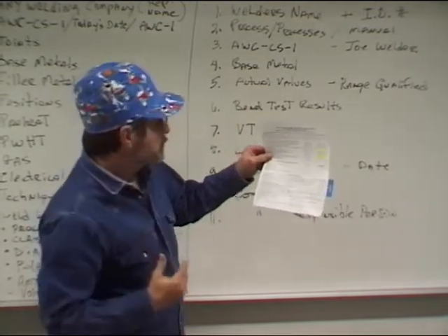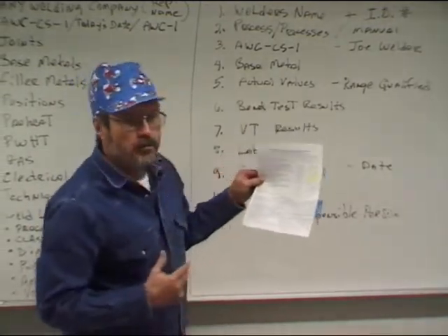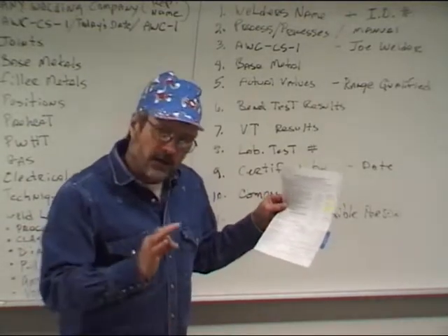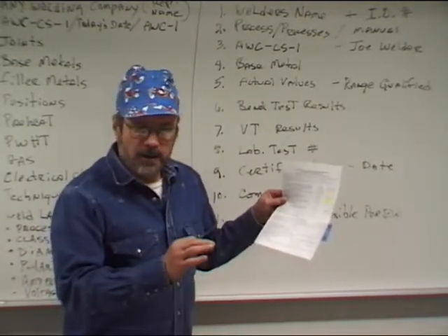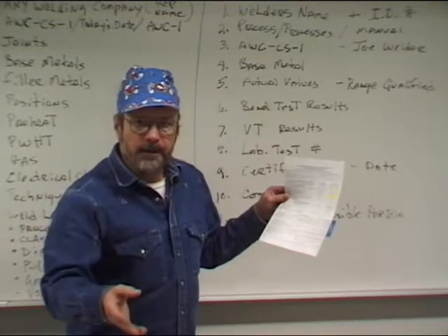Those are the paragraphs, again, in Section 9. And a lot of companies will do both. They'll have you do a test coupon, and they'll x-ray it, especially on that 2-inch. They'll x-ray it, and then they'll go ahead and bend it.